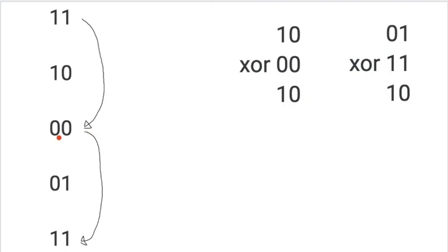Okay, what if we do it for a later position? For example, moving from 0, 0 to 1, 1 clockwise. Well, the intermediate is once again 0, 1, and then it's 1, 1. XOR them together, it's the same thing. That's because when you XOR an intermediate and the final detente, you'll always end up with a constant. This constant remains constant, no matter in what section of the code is happening. It only matters the direction of which it's rotating.